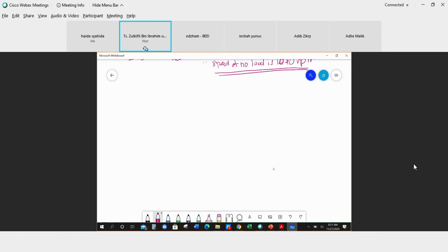No armature reaction. I already told you about armature reaction. I explained what armature reaction is. So, assuming no armature reaction, it means we can use the calculated IF without needing to find the effective field current. So what is the speed at full load? What is the speed regulation of the motor?